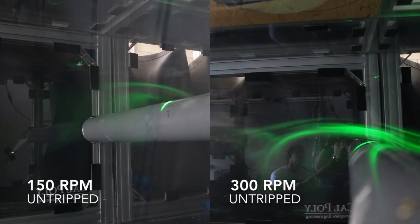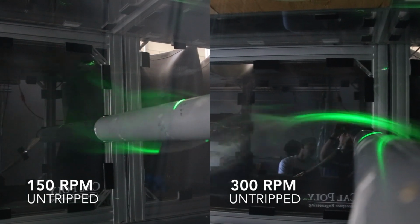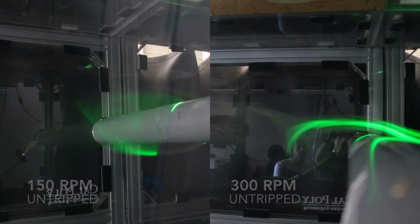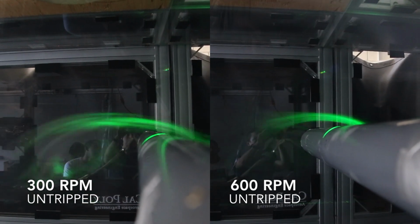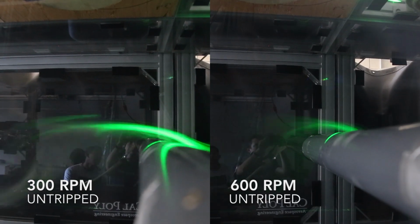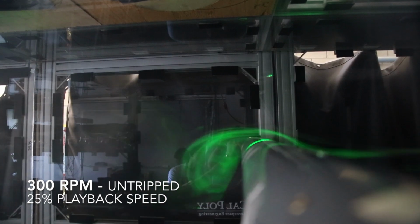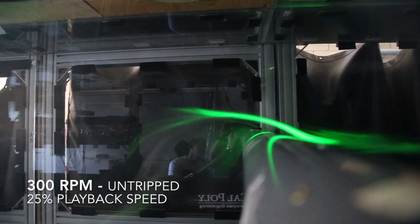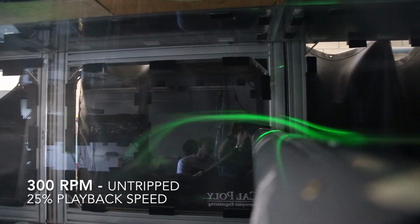The flow is able to travel in all directions, not just over the face of the cylinder. If a sphere was used instead of a cylinder, similar coefficient of pressure and coefficient of drag values would be recorded, and the flow characteristics would act similarly since the curvatures are identical. However, there would be less asymmetry since a ball is symmetric around every axis and the cylinder is not. The Reynolds number for the ball and cylinder would be the same, assuming the diameters of the ball and cylinder are the same. This is due to the Reynolds number being calculated using the length of the diameter and the fluid conditions, which most likely would not change.